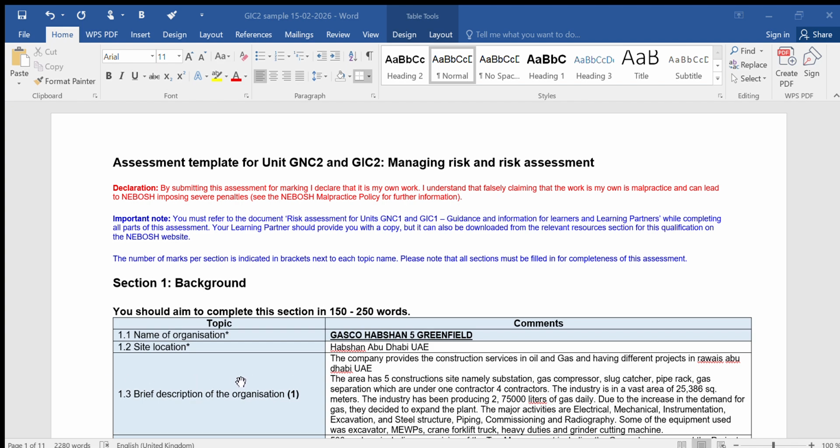General reason for prioritizing this hazard. Severity: exposure above 130 dB can cause immediate and permanent hearing damage. Now likelihood: continuous. They are continuously exposed to the noise hazard in the workplace. And the number of workers exposed is 500.